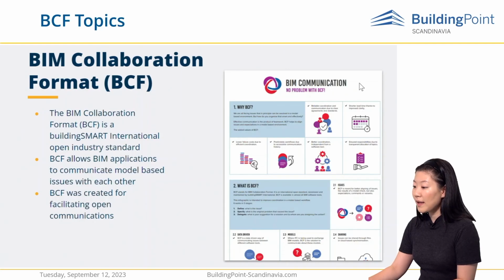And such communication can be made in various ways, by emails, drawings, markups, but the most effective way is using BCF files, BIM Collaboration Format files, an open industry standard from Building Smart International. Trimble Connect BCF topics can gather all the design issues found in our project. In BCF topics, we will store, manage, and also track all the issues.